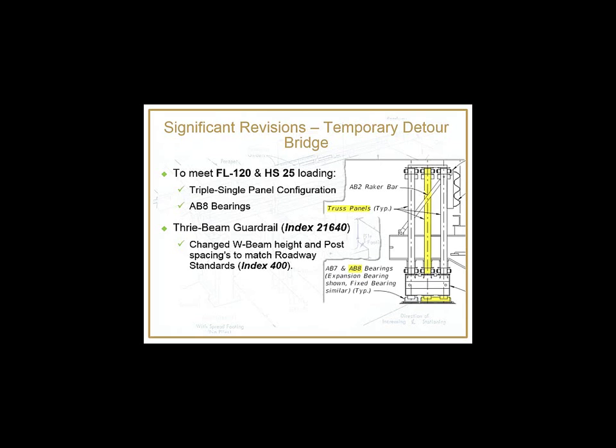The department owns all that, the 300 series Acrow bridge, so we have the material available, and there was a little, I guess, mistrust on our maintenance department for permit truckers to comply with some signing. So what we have done now is change the design criteria to be full HS, to be HS25, which is going to easily accommodate the FL120.